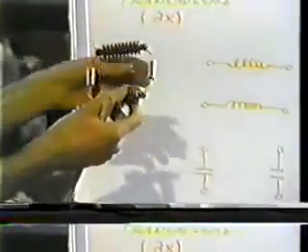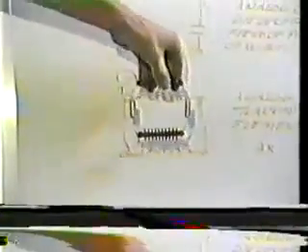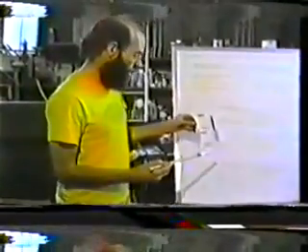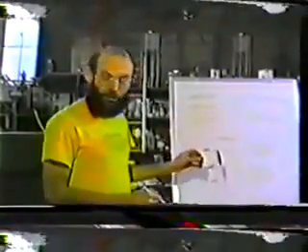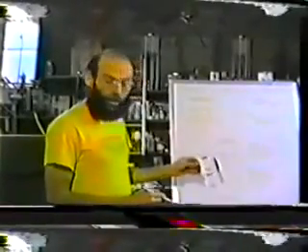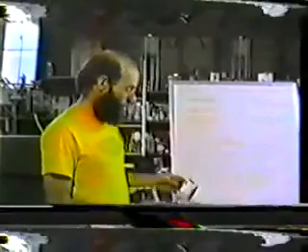And we have some radio frequency inductance coils of 10 millihenries, and we have some high Q pulse capacitors of 0.047 microfarads. This constitutes one element of transmission. And of course, we can propagate either longitudinally or transversely, and we're going to stack these elements up to symbolize and synthesize these 2 forms of waves, and then we're going to get in there with some rather unique detectors and some conventional detectors, and even use our fingers and determine exactly what's going on with these things and see how this correlates with our previous measurements of actual transmission structures and not their analogs.